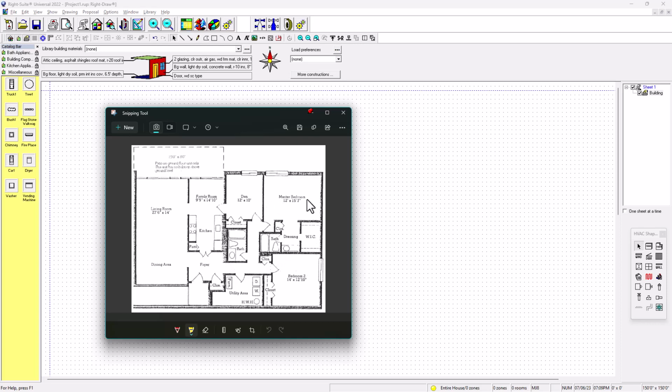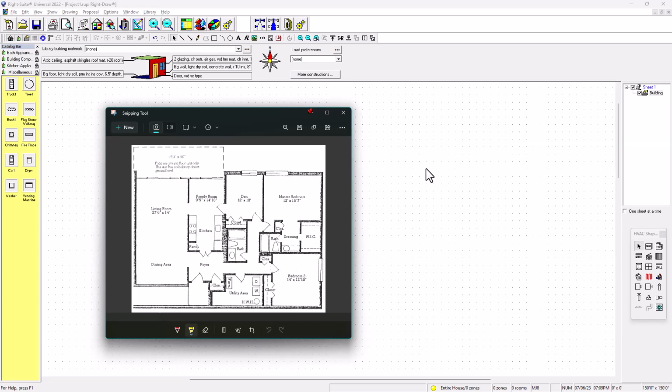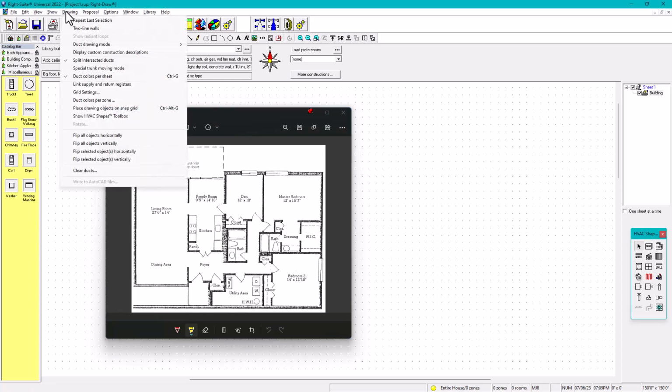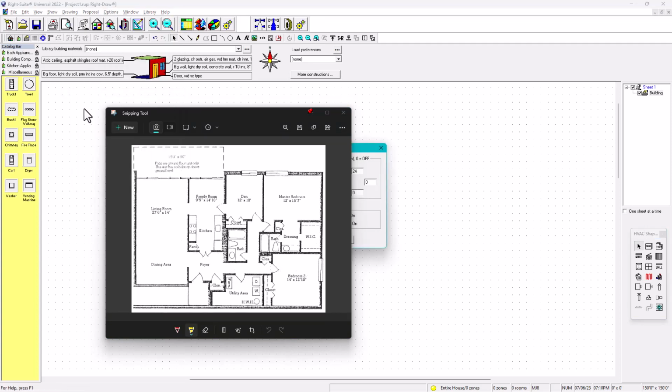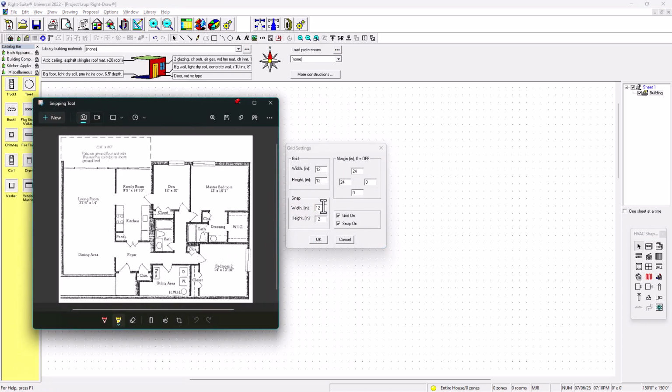All right, so in order to start drawing the rooms, I need to make sure of the grids. What grid is my grid system? Do you remember in my other videos this is 1 1 1 1? So let's check in here. If you go to drawings, in drawings you're going to be able to see grid settings, right? So go to drawings, go to grid settings. Under grid settings, what do we have in here? Let's check. In here we're going to have 12 12 12 12. So the distance between each dot is 12 inches.